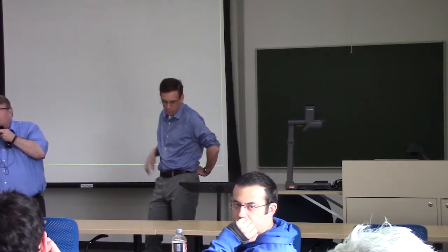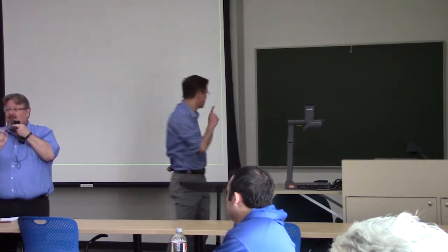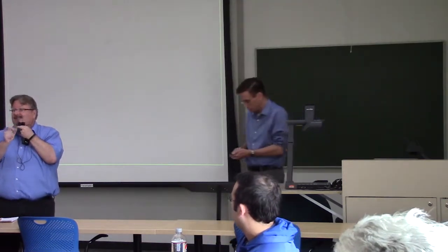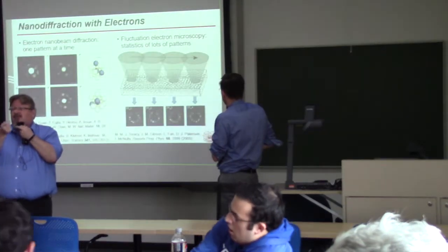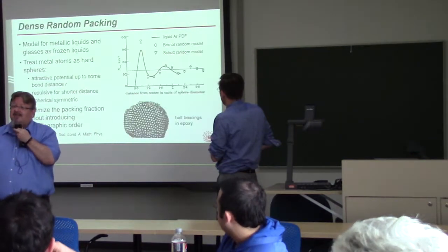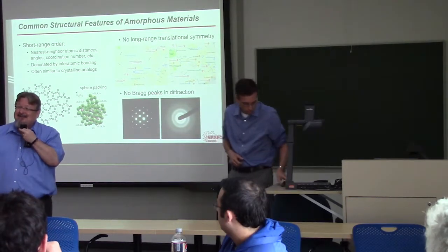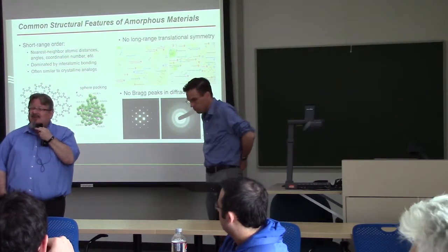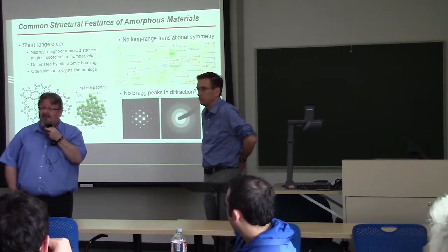Yeah, so those Angstrom beam diffraction experiments are done on metals, so they're really trying to match the probe size to the size of a nearest neighbor cluster. So they're using like a 4 angstrom probe, that's about two angstrom bonds across. Now if you can make an angstrom size probe and use one of those to do diffraction from a glass, what you find out is that the glass is made of atoms. And you kind of knew that already, so there's not a lot of useful additional information at super high spatial resolution in electron scattering or electron microscopy from glasses.